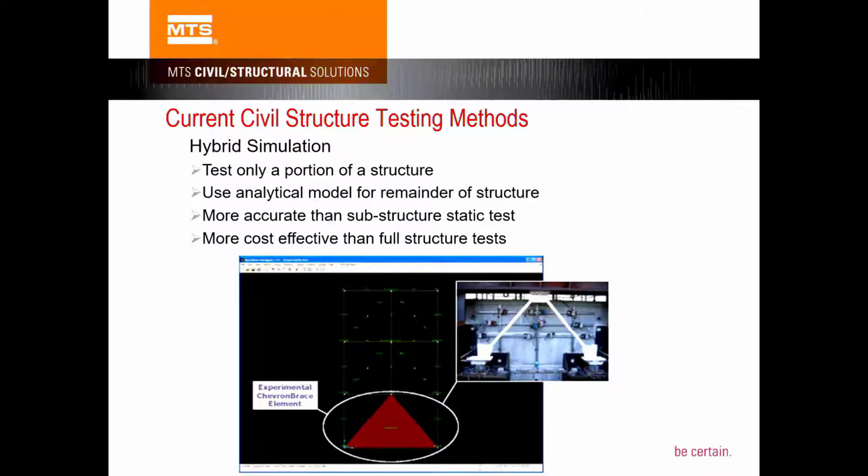So it has a numerical substructure and a physical substructure. So it is more accurate than pure FEA because the hard-to-model component is tested. It is more accurate than the quasi-static test, because the model provides the dynamic load time history.